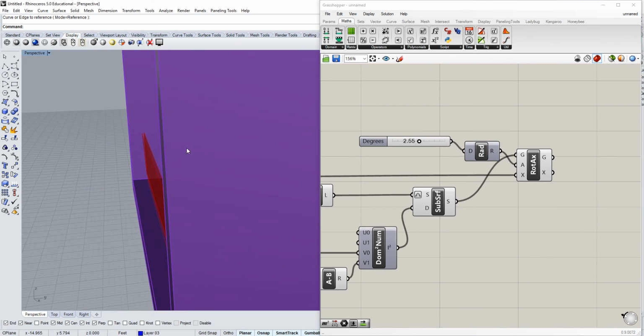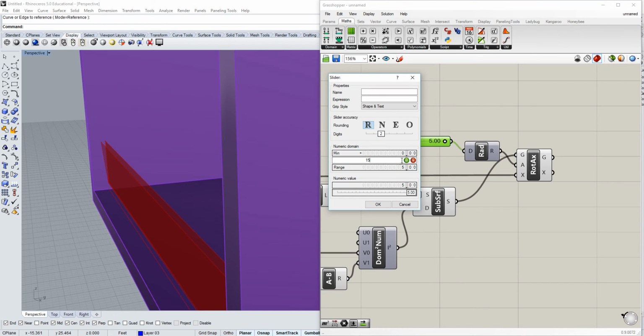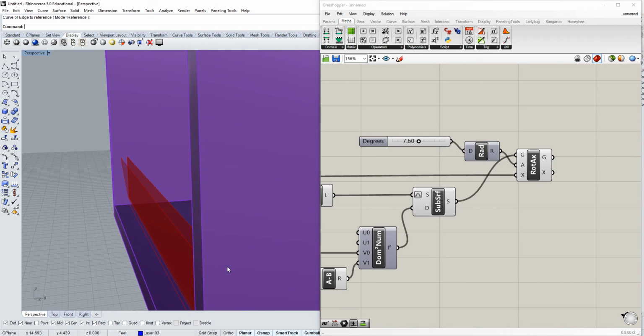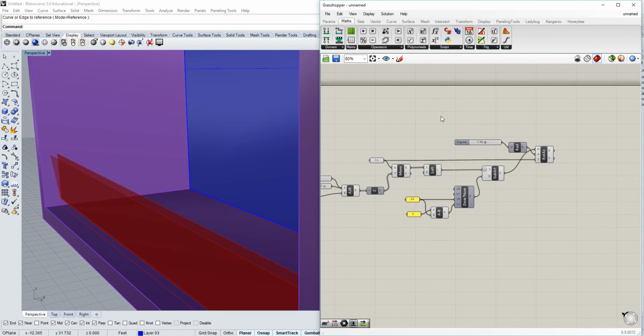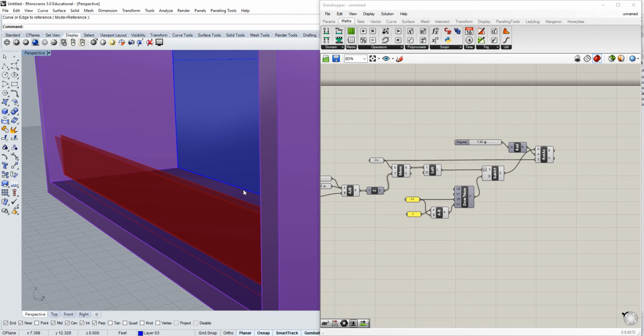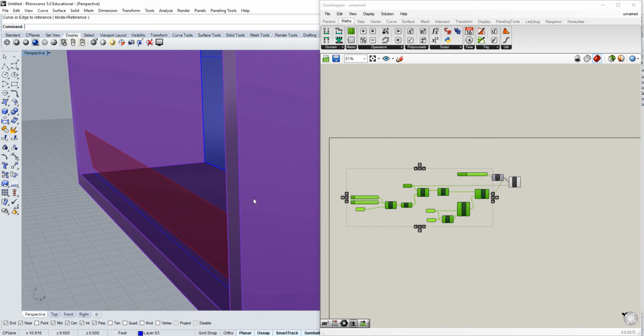There you go. And what you're going to see here is that now I can go from my original spot all the way out to 5 degrees. Oh, wow. Okay, so that's a lot smaller than I thought it would be. So we can change our maximum value to 15 degrees, and then we can tilt it out a little bit more. Now the truth is it's not really going to tilt very much because we're going to have a handrail in there too, probably. But this looks like probably enough for me right now. And at this point, I have a lot of old geometry here that I don't really want to see. So for now, I'm going to turn off everything except for the final surface that I generate right here.